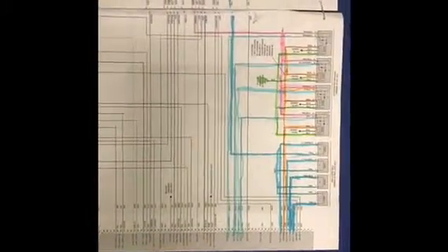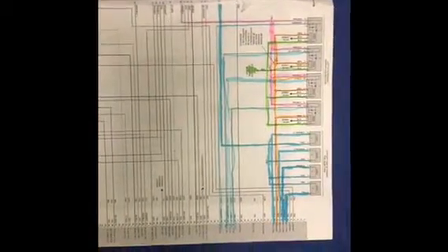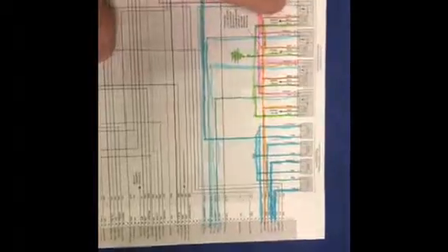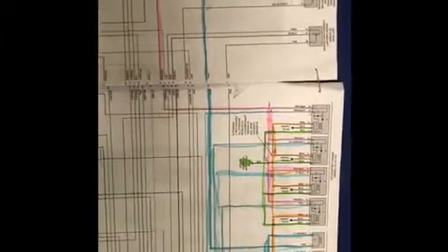All right, here we have a wiring diagram for a Chevy HHR, and we're going to go over how the injectors get power, ground, and so forth. We'll just do one injector to explain it. You have our power, which is highlighted in pink, and goes back over to the underhood fuse block. You have an initial module fuse, 10 amp fuse.